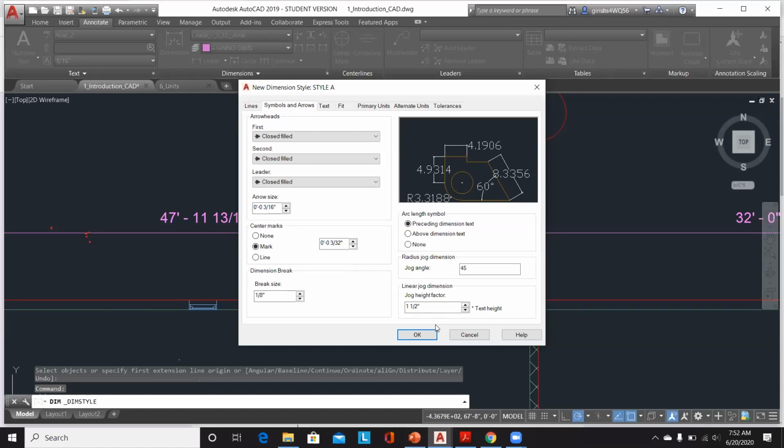But if you're following the ISO standards, there are standards already given that define the text size and the orientation angle it should have for particular drawings. I would highly suggest you take those standards, follow them, and convert the standard settings into AutoCAD using these parameters, and then the standard text will be visible from the paper space.